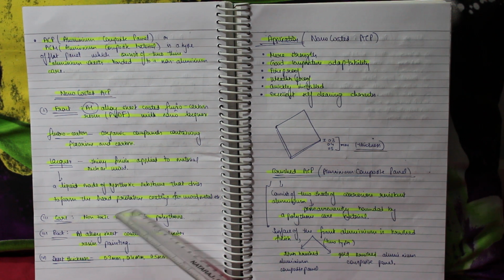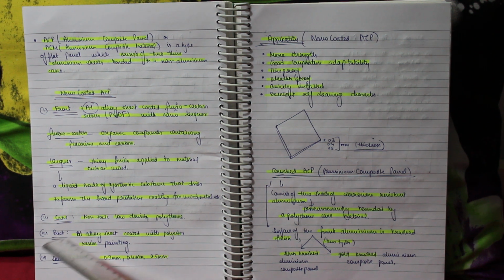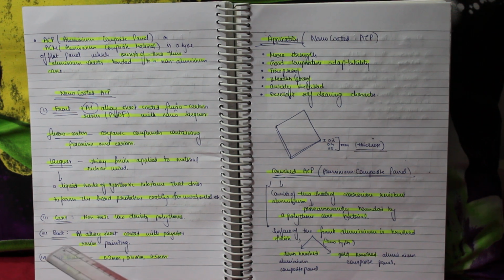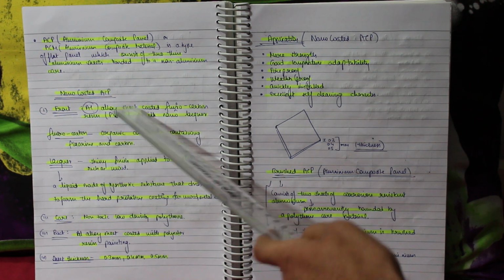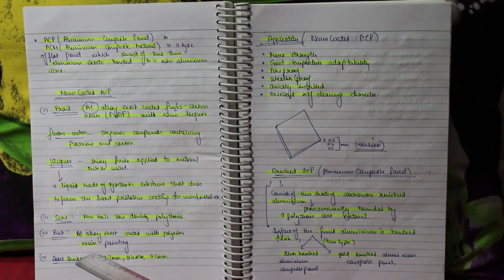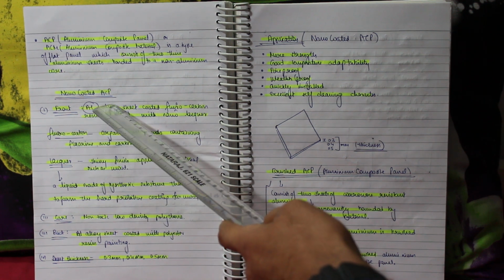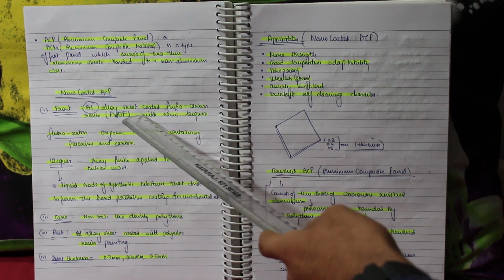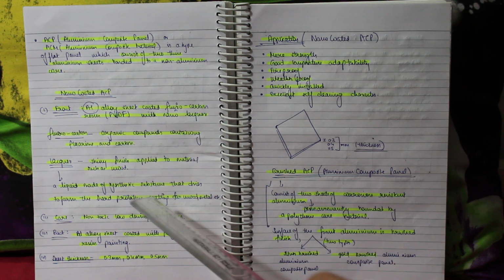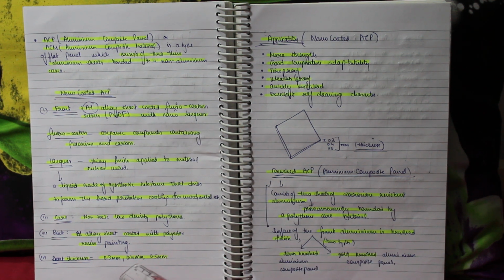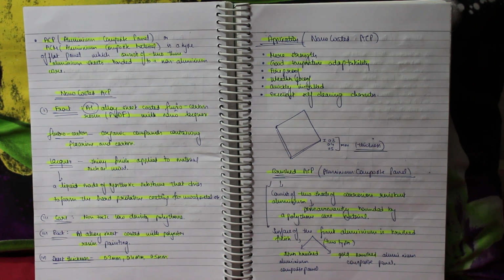Here it is a low density polythene, and the back you can take as the front panel as well, but depending upon the usage you put it as a back. The aluminium sheet is coated, so the front and the back are just the same, but depending upon the usage, if it is used for design purposes, the front would automatically be coated with lacquer so that it becomes more attractive. The thickness of the complete sandwich sheet is not more than 0.3 mm, 0.4 mm, or maybe 0.5 mm.